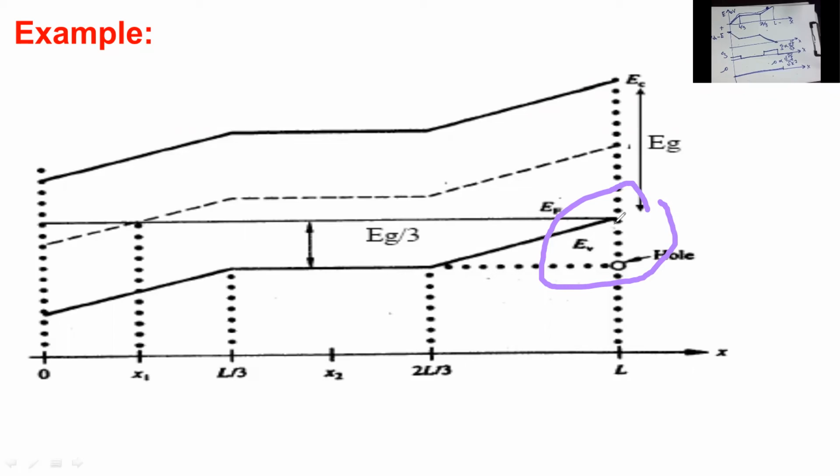Do you remember this point at which N_A equals N_V? E_F minus E_V will be equal to 0. So we have what's called an overlapped Fermi level with the valence band. So this is another important example, my dear students. Perfect. Do you have more questions?